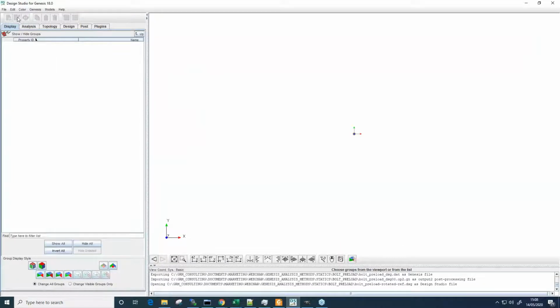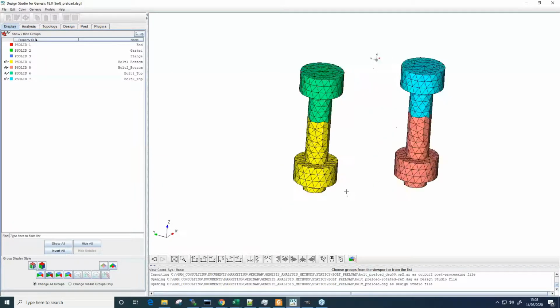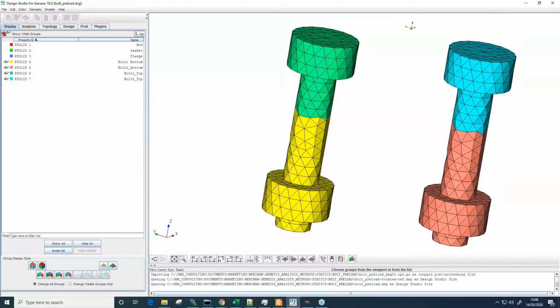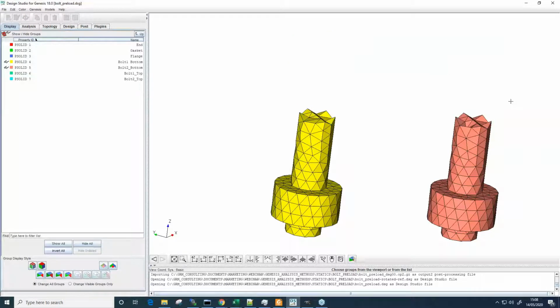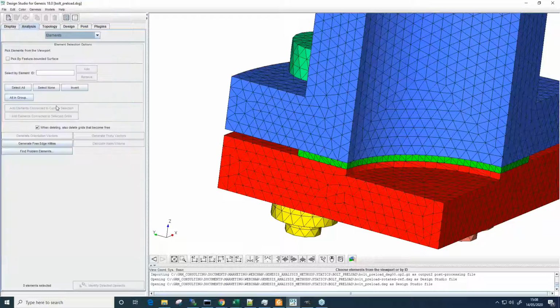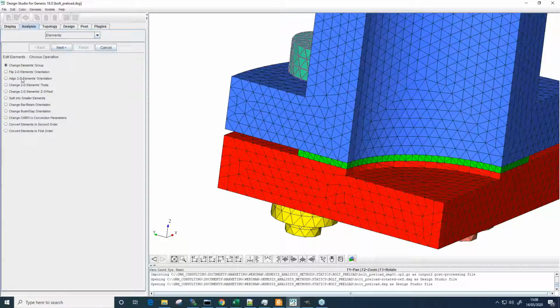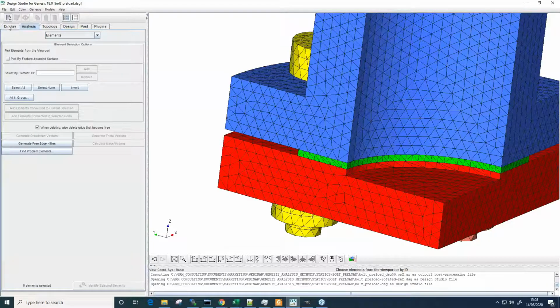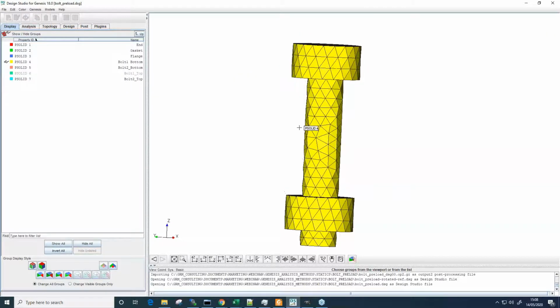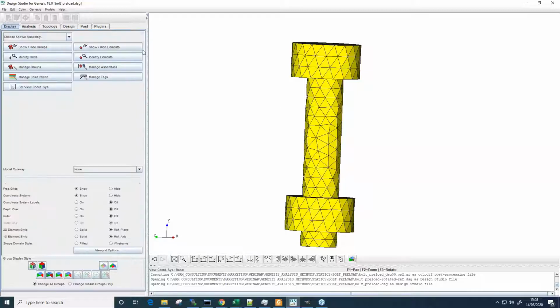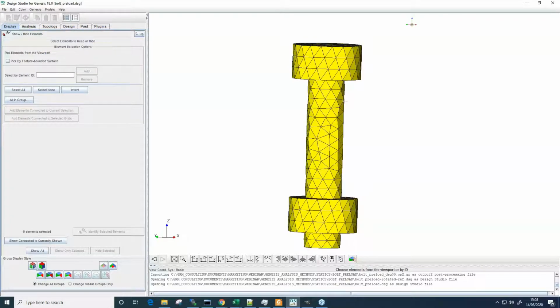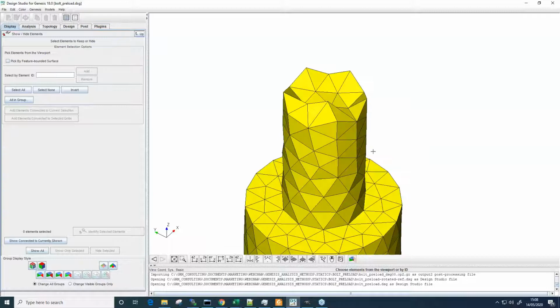So when you mesh the bolt that we just saw, if I go to any of these, you just simply mesh that as one. If you've meshed that as one single part, in this example it's been split into 2 groups, so it's very easy as a tutorial to hide them. But equally, if I put them into this group, so say, for example, I only had that there, then the process of creating the data is exactly the same. What I do here is I simply show hide elements, and I can just choose where I want my section to be, hide the elements, and then I pick these faces here, again on the bottom surface, and it will do the splitting automatically. So it will create new grids, create the bolt element, and connect it all together in the way we want it to. Okay, I hope that answers your question.